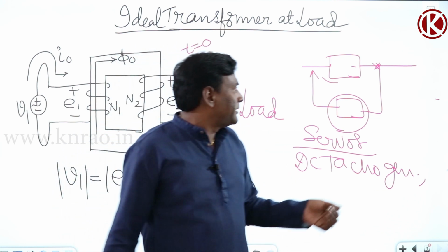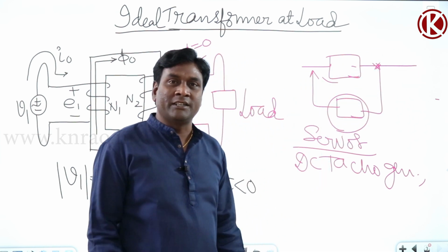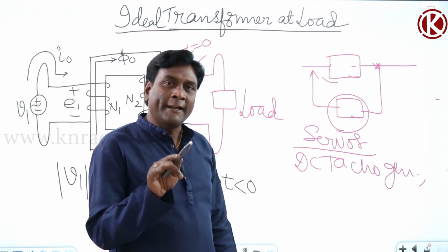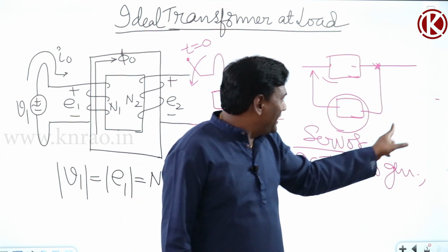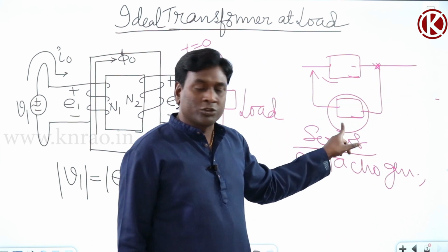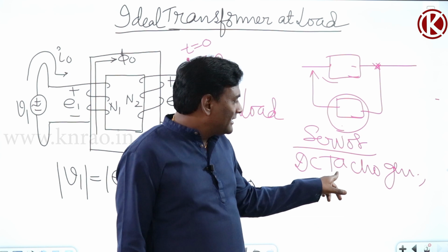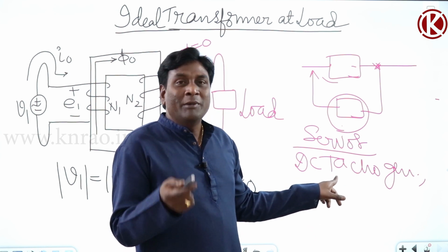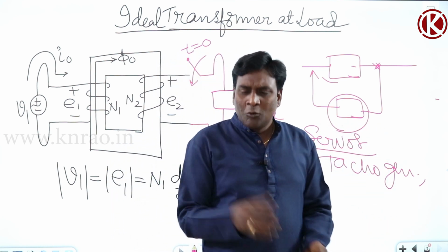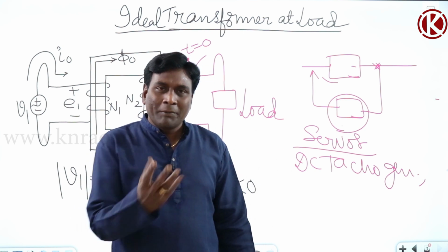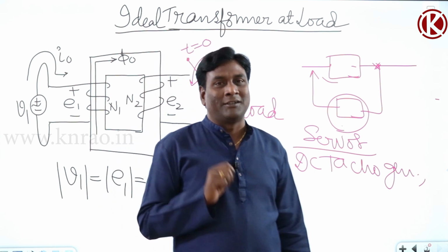For example, if you laminate a machine, it should be to reduce eddy current losses; efficiency matters for this. But a DC tacho generator, a kind of servo, will also have a laminated core. Now can I say that the DC tacho generator is laminated to reduce eddy current losses? No, because what is the power handling capacity of a servo? Information. What is the power handling capacity of an ammeter? Of a voltmeter? It is nothing. But what is important? Information matters.